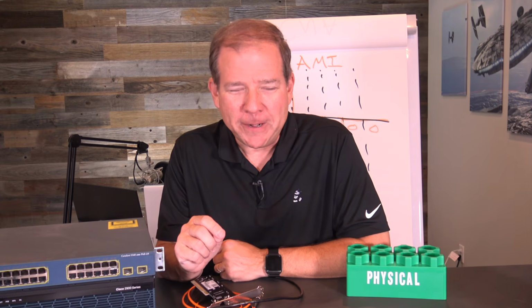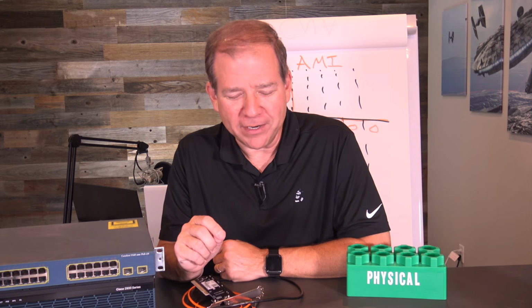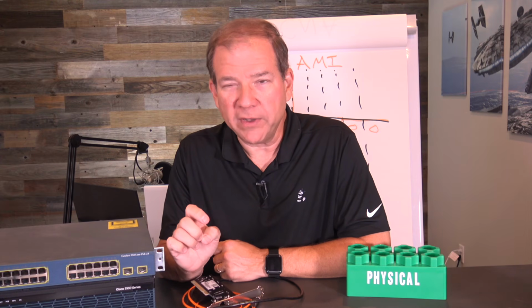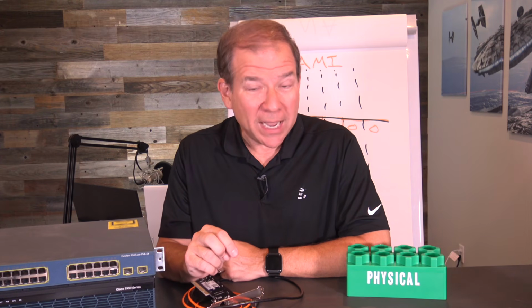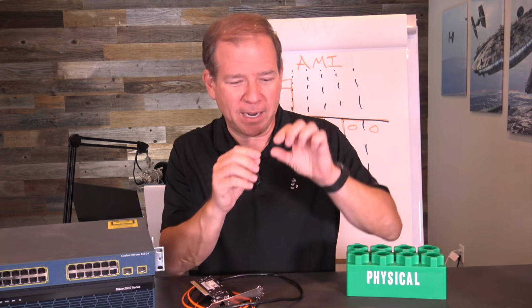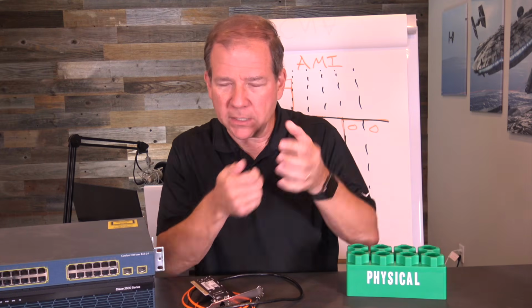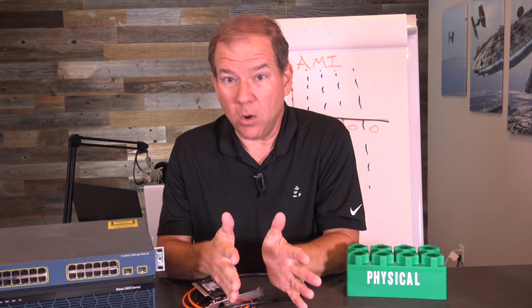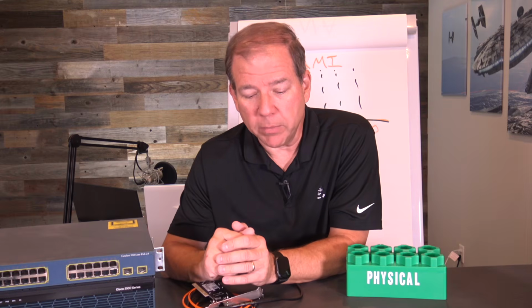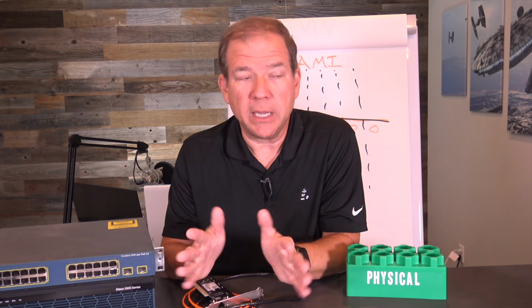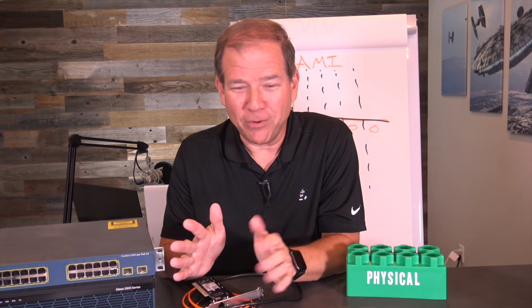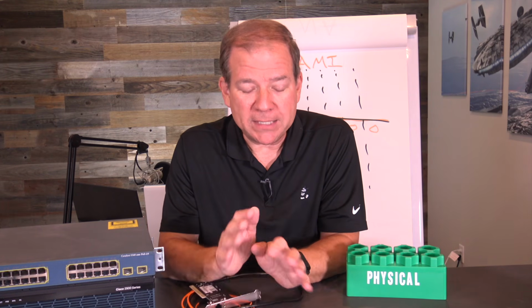But when we call it an RJ45 jack, I know I'm being overly technical here, but just to be super technical, it's really not an RJ45 connector. There is no RJ45 standard. There is an RJ45S standard, and it's not this. It looks like this, but it's got an extra little notch in it. It's a keyed connector. It's not what we think of as an RJ45 connector, but this is commonly used in the industry. I'm perfectly fine with you calling this an RJ45 connector. No worries there. But that's an example of a connector.